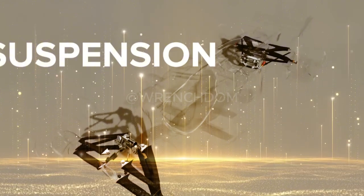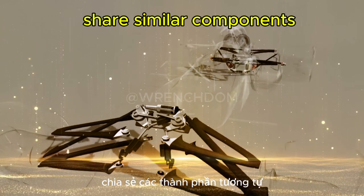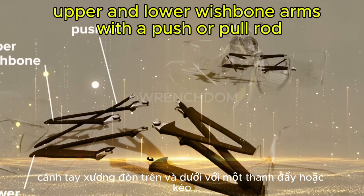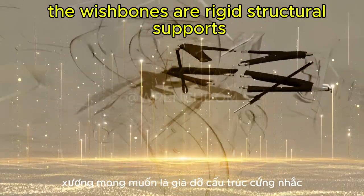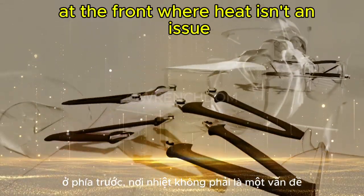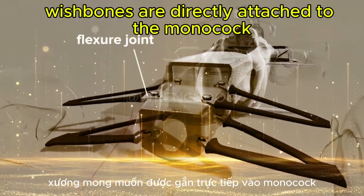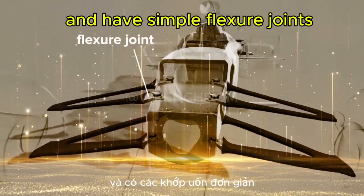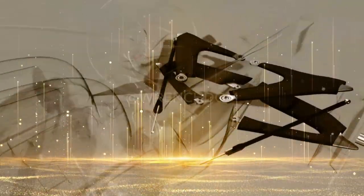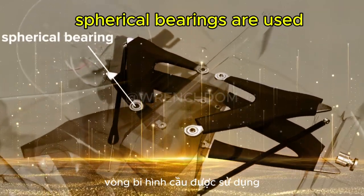Suspension. Both front and back suspension setups share similar components: upper and lower wishbone arms with a push or pull rod. The wishbones are rigid structural supports with limited vertical travel. At the front, where heat isn't an issue, wishbones are directly attached to the monocoque and have simple flexure joints designed to bend under load. At the rear, where engine heat can be intense, spherical bearings are used.